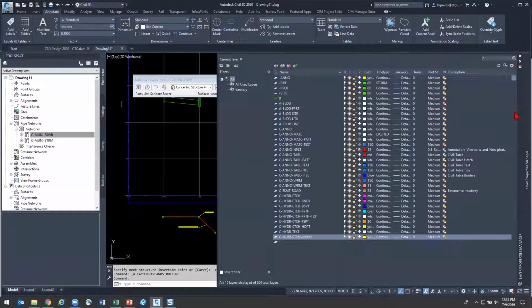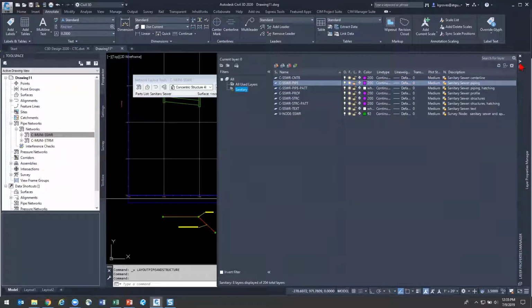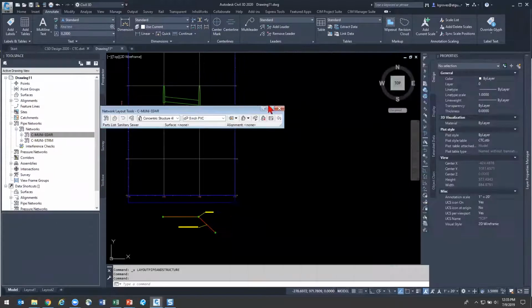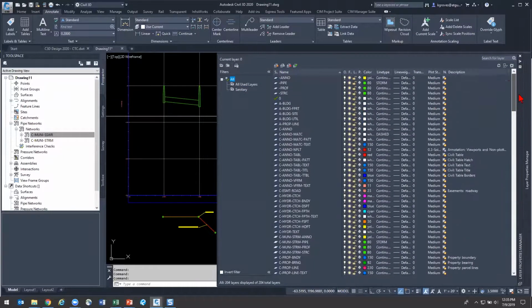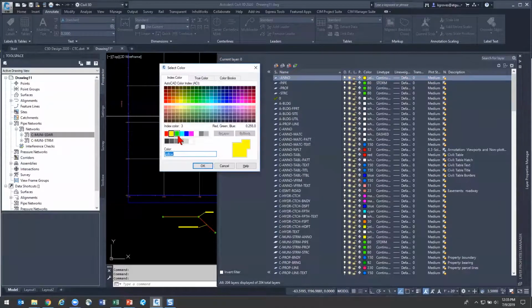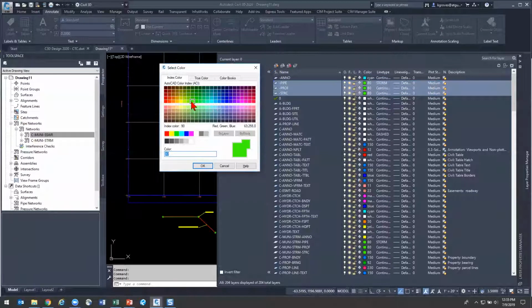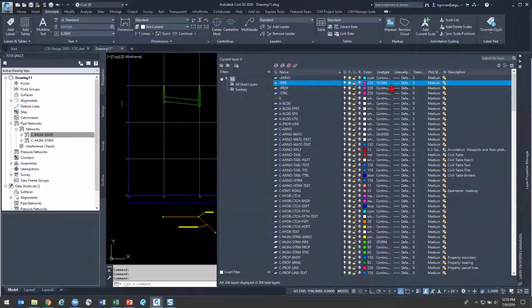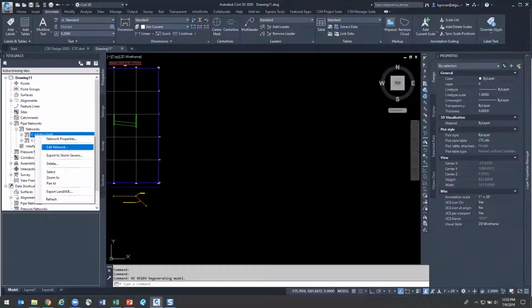So I'm going to do the same thing here, but not quite yet because I need to go back. Now that it's time to create my sanitary stuff, these base layers are going to inform how that's going to work. So my current sanitary is set to color 200. That's fine. I'll use a slightly different shade of pink for my base layers. I'll do a cyan annotation. We'll get nice and bright with color 200. I'm going to change my line type for my pipe from storm to sanitary. Go over to my sanitary network, edit it.